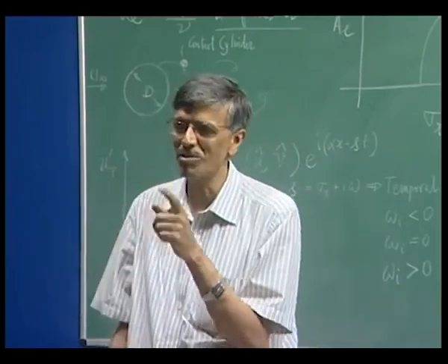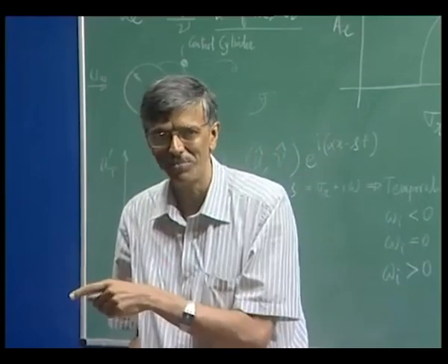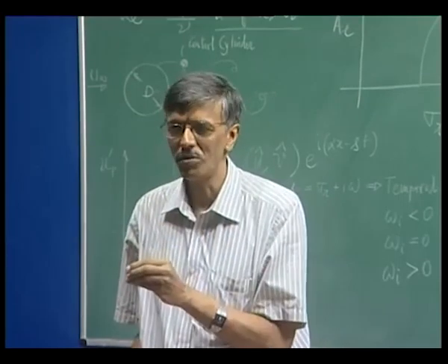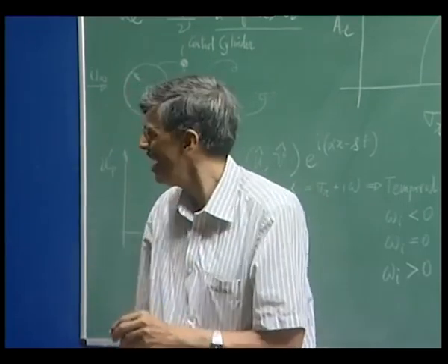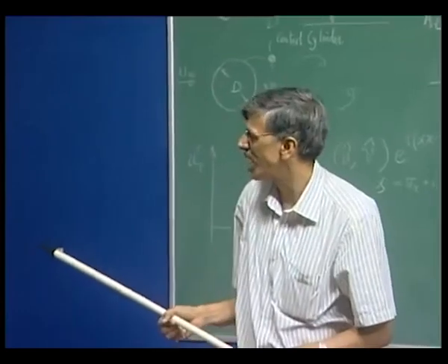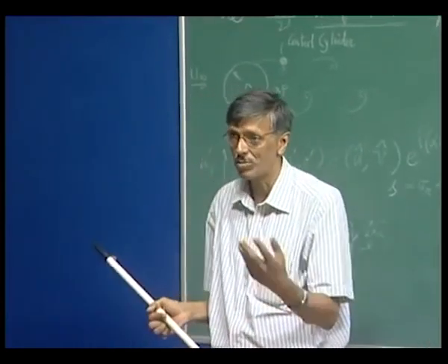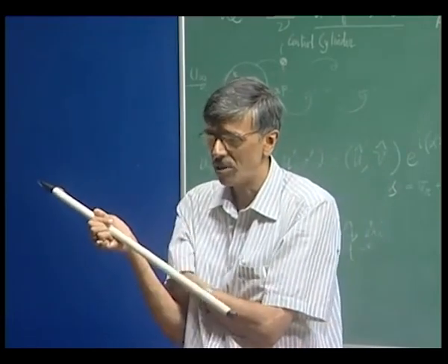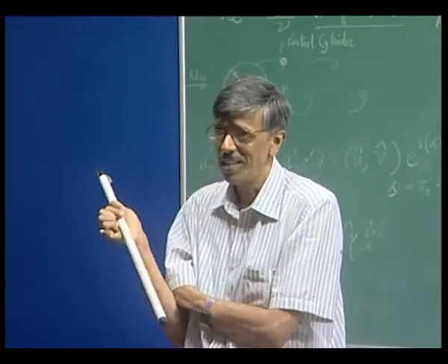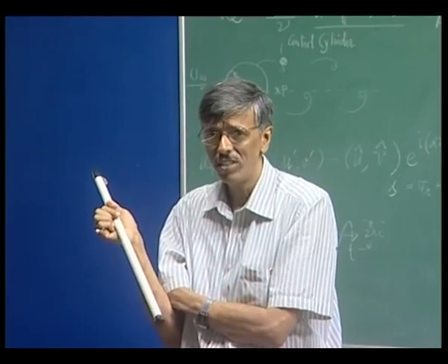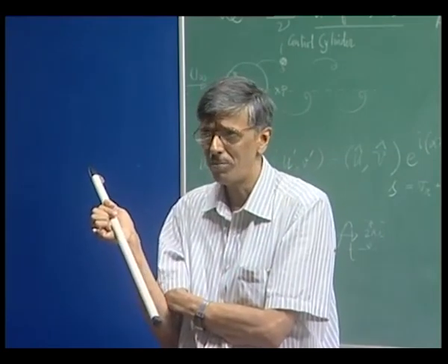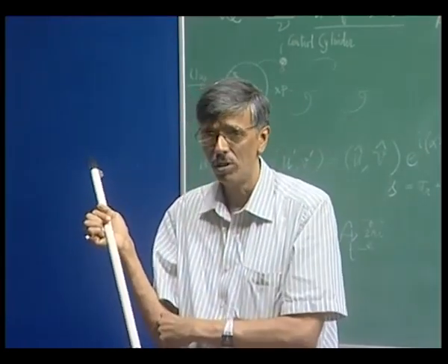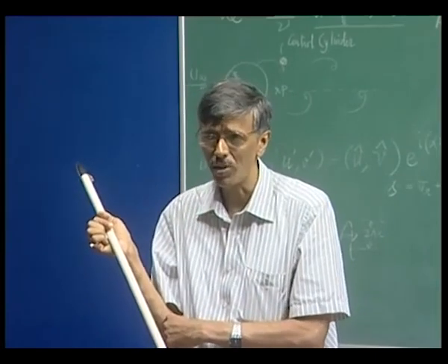And this observation of Courvoisier was picked up by Strykovsky for his PhD thesis. They wanted to find out what is the role of the control cylinder, how you can control it. And this was what we actually studied numerically. And they did those experimental studies. This is that famous JFM paper of 1990, Strykovsky and Srinivasan. They showed not only that you can change the shedding pattern by putting in a small control cylinder, you can do the same thing by putting in a heating element also. So looks like there are various ways of flow control.